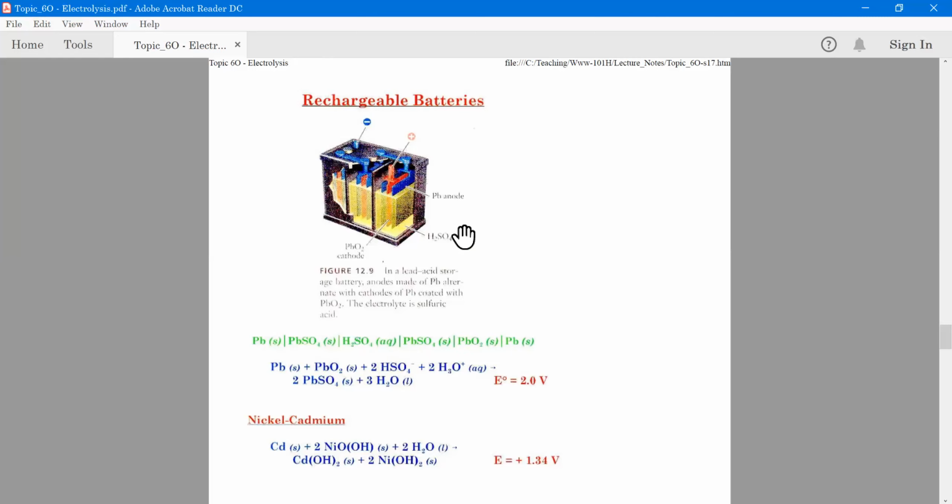So if the battery is used efficiently and it starts the engine and it's not weakening itself, then it doesn't take very much electricity to recharge the battery and get it back to its original state. And it's for that reason that there has to be something called a voltage regulator that's in series there, so the battery cannot overcharge, and that would start to corrode away all the lead. So, but the overall system is a very unique one that has proved its worth by still being in use more than 100 years later.